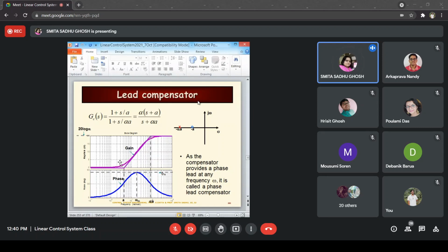Each time you get one value and you plot it, meaning you put the point on the Bode plot. By joining those points, you would be able to get the overall magnitude response. This, of course, is for a specific system, but what I wanted to show you is this framework, where you get one point at a time by using that experiment, right?